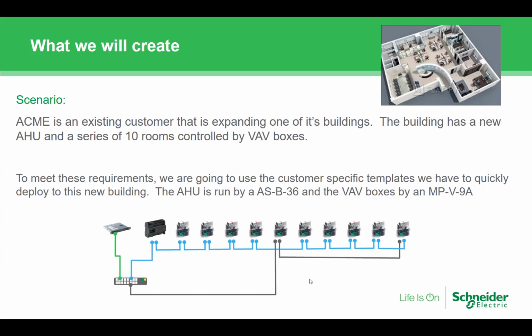I could create an image of each VAV controller and send a technician with the eCommission SmartX mobile app out to get the VAVs up and running as soon as they have power. They could be running and balanced in a really short period of time.